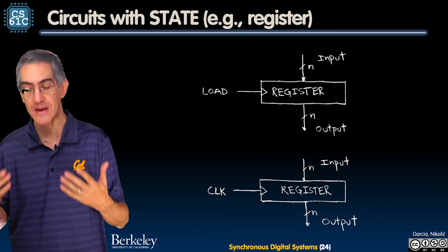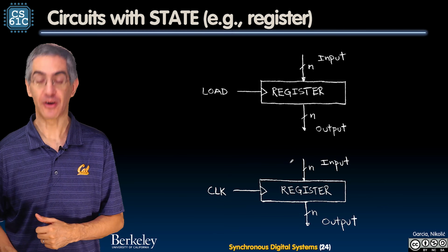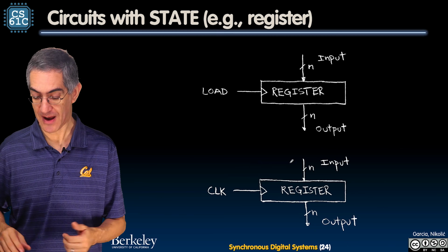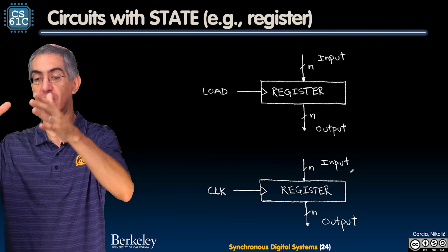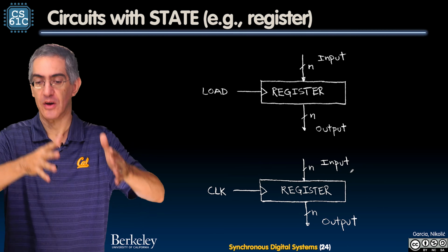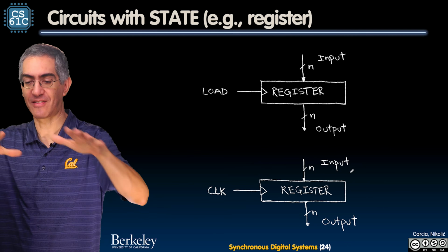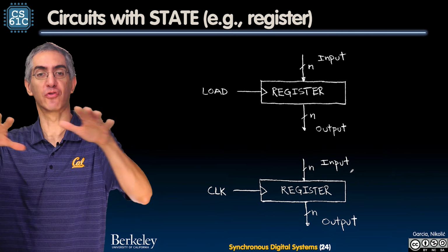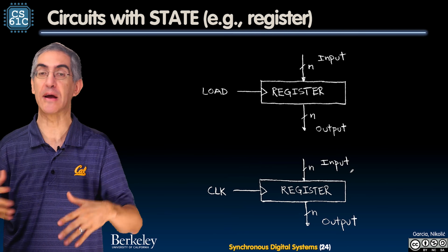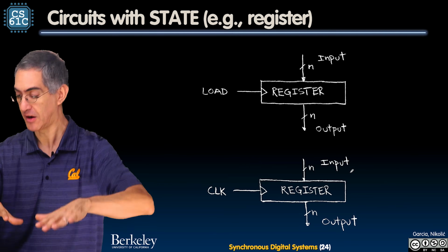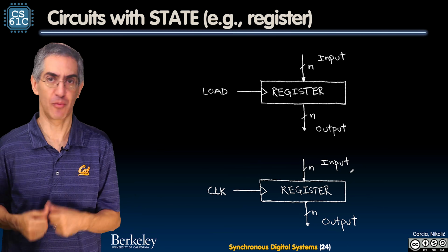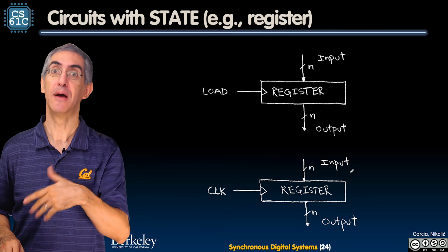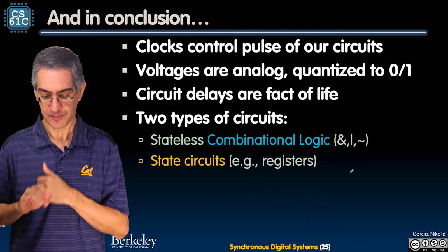And so normally we're going to clock these devices, and having them clocked is great because now there's a rhythm and now data's kind of moving in chunks, like an assembly line. Ka-chunk, ka-chunk, ka-chunk. They move to the next stage. Everything just kind of moves to the right. So that's going to be great as we build circuits. We're going to have our data kind of ka-chunk to the right. That's exactly what we'll use this register that's going to be clocked. So we typically clock our registers, not always, but we often do.